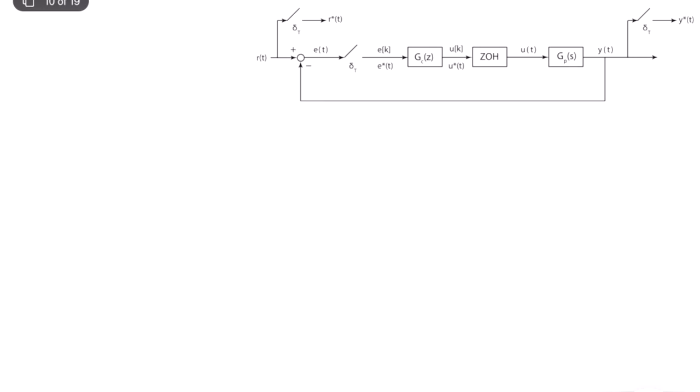In the previous two videos, I talked about the concept of pulse transfer function and how we can analyze different kinds of topologies using the concept of pulse transfer function. Now, our goal is to analyze a real physical digital control system from the perspective of pulse transfer function. This is a typical fundamental block diagram topology that we want to analyze in this course.